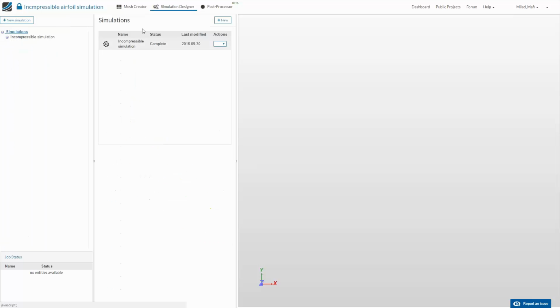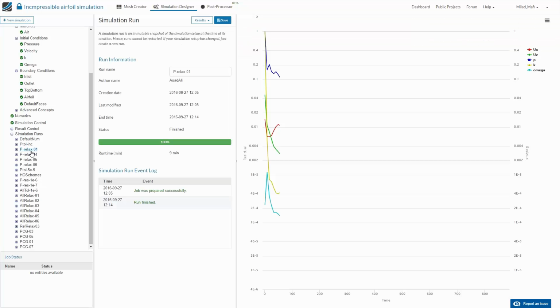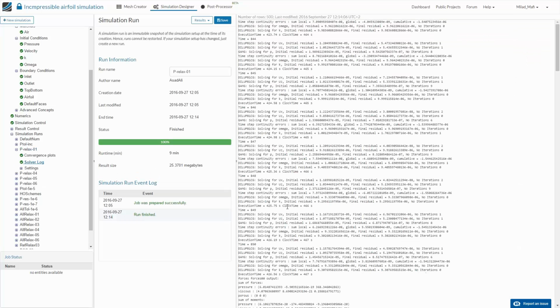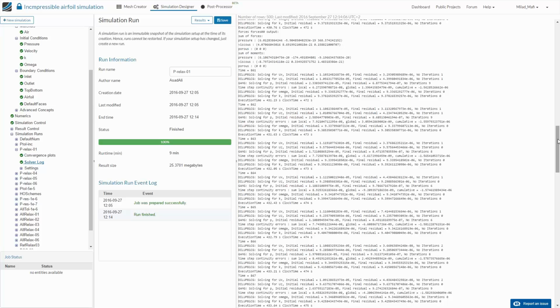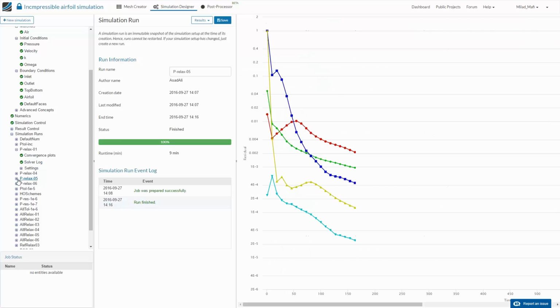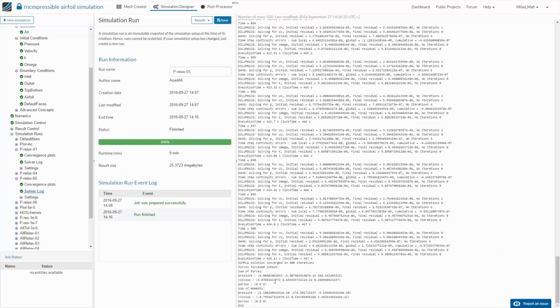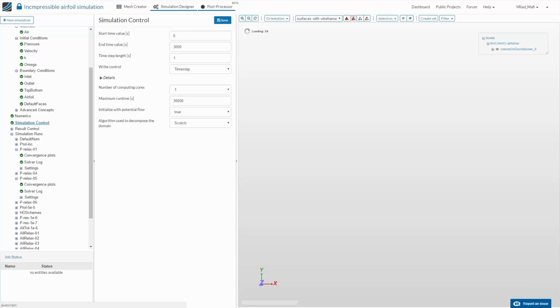And the reason is related to our tolerances. If you take a look here, it's a solver log. You can see that SIMPLE solution converged. That means that one of our convergence criteria defined before was reached. And here, it converged after 9 iterations. But basically, the setup was for 3000, so it really shows the impact.